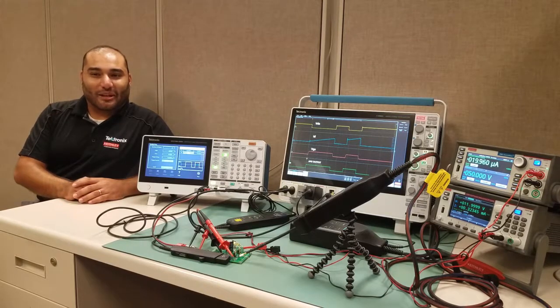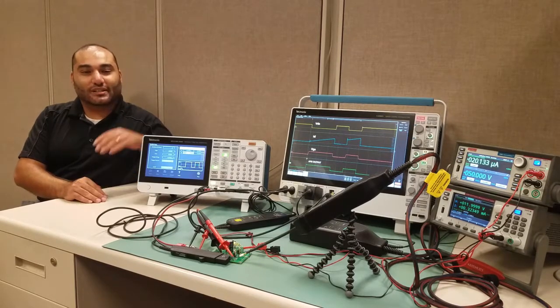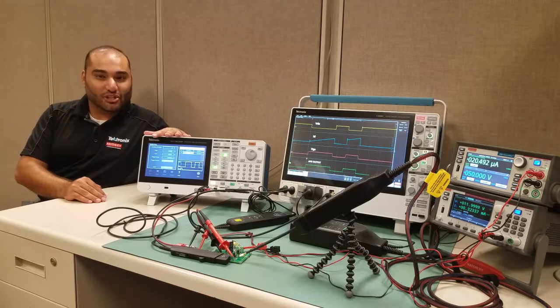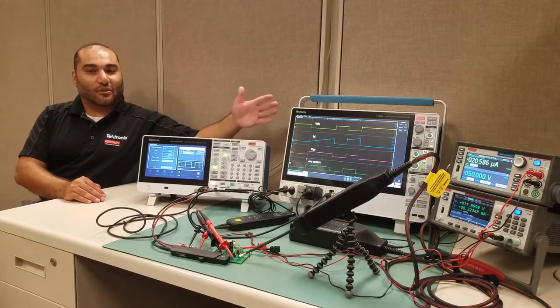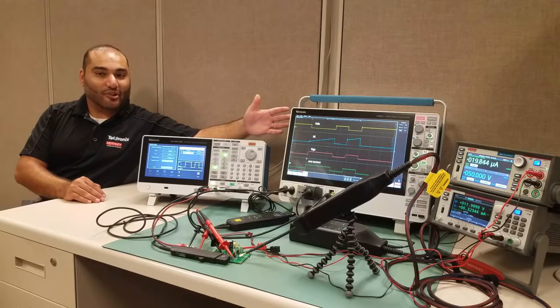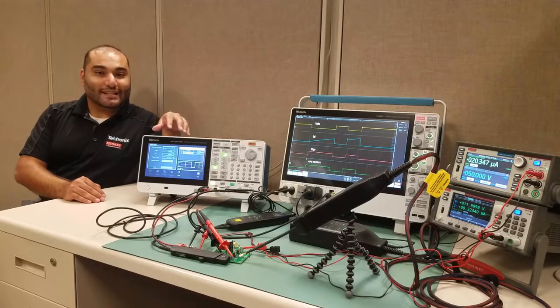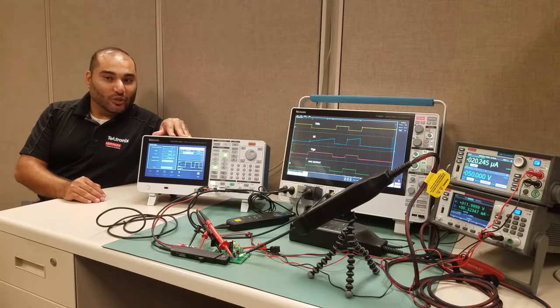Today, I'll explain what the double pulse test is and why engineers perform it. I'll show you how to use the double pulse application on a Tektronix arbitrary function generator, AFG31000, to set up your pulses in less than a minute. We will also show measurements on a Tektronix Oscilloscope, MSO5, to measure our parameters. We will be doing this test using an ST micro eval board, a Keithley SMU, and a Tektronix ISOView probe, a current probe, and a differential probe.